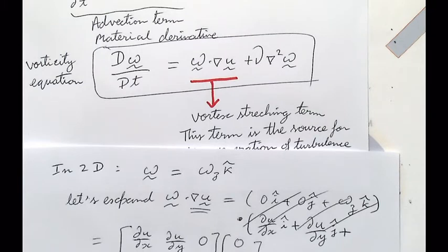The viscosity is causing the dissipation. Yes, by the viscosity. It's the same idea as if you put your hand in a bucket of water and disturb it. It will take maybe a few seconds to die out. For the huge ship that's maybe half a kilometer long, it can take minutes. The reason is that any disturbance you introduce into fluid is killed by viscous dissipation. The viscous diffusion is the term that destroys the kinetic energy that we introduce.